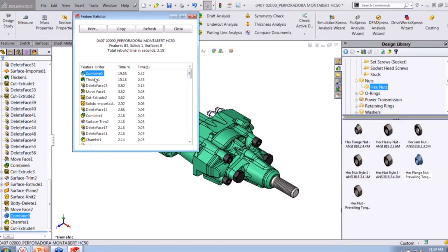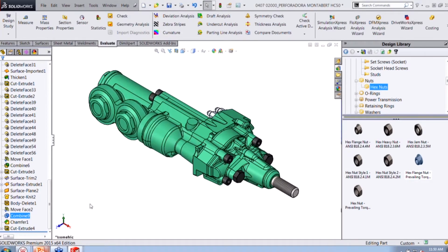So you can do that all the way going from top level, run assembly visualization. You can see which has the most rebuild time, what's the most mass, and so forth. It allows you to visualize the assembly itself, and then also go down all the way from part level down to the feature level. Okay, and then also tell you your rebuild time, how many features are in here, etc.